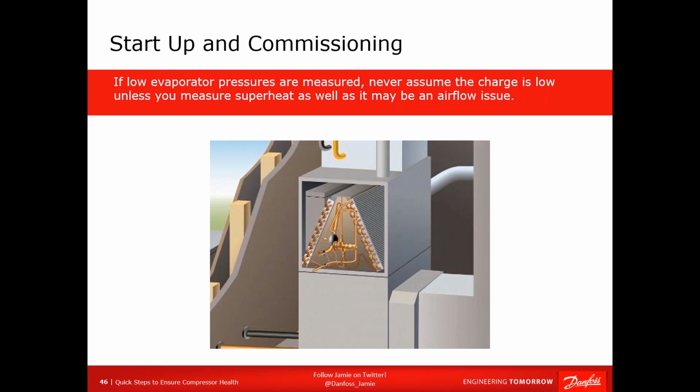All right. And once again, never add refrigerant until you verify system charge with either superheat, subcooling, and evaporator temperature and pressure. Okay. And make sure you verify that airflow. If your airflow is low, so is your superheat going to be. All right. So don't add refrigerant just because you see a low evaporator temperature.